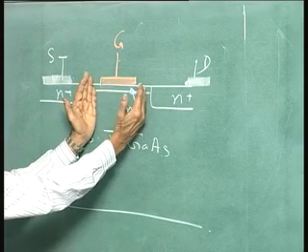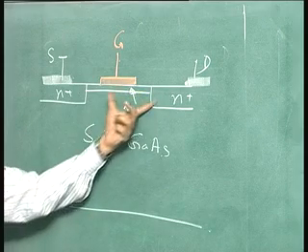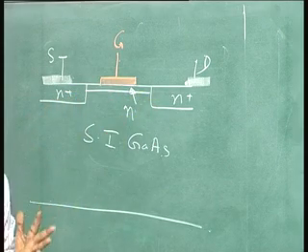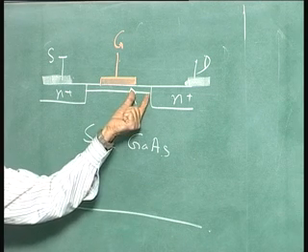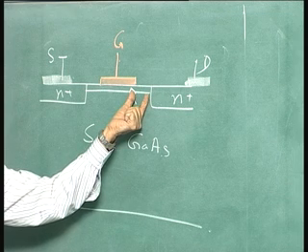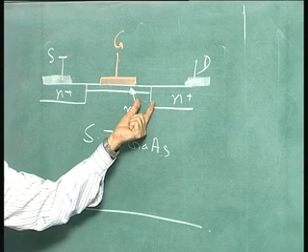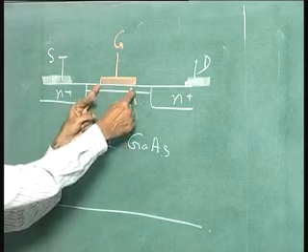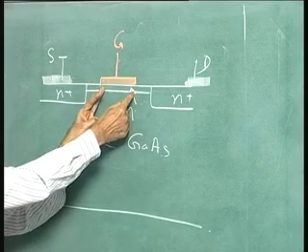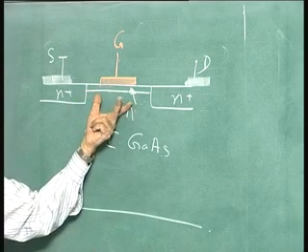If I reduce this distance and also cut this down, keeping the gap same, because the voltage is applied between the two, the fields are higher. Okay. So, the experiments that they have reported are, in one case this is kept at 0.3 microns, one curve, and another curve where this is kept at 0.15 microns. So, in the case where it is 0.15 micron, if this gate length is 0.25 micron, 0.25 plus 0.15, 0.55 micron is the gap.